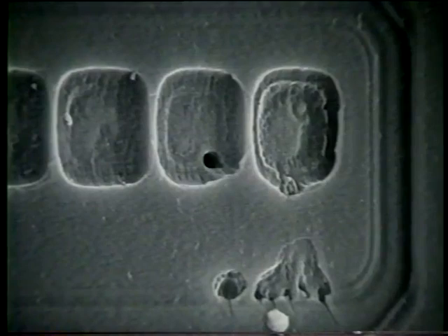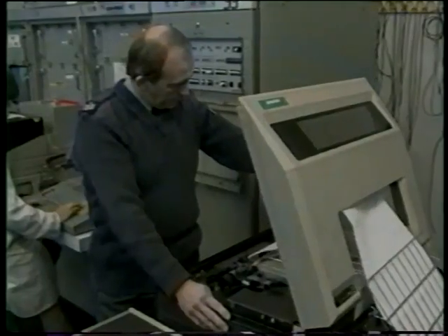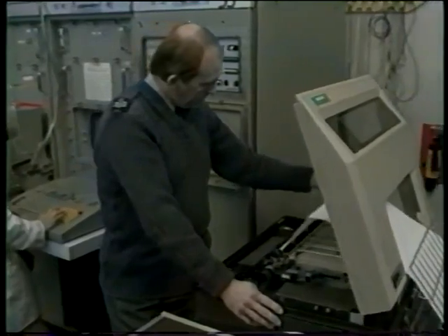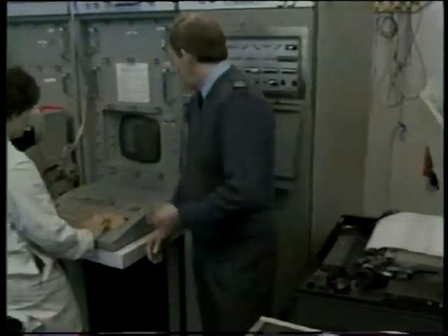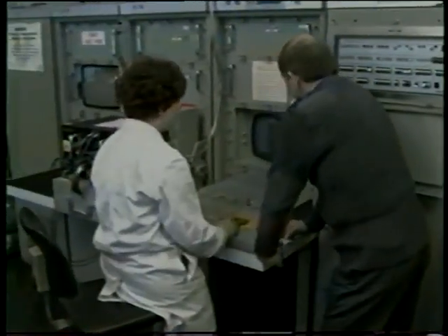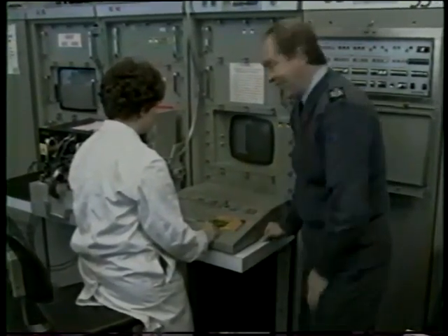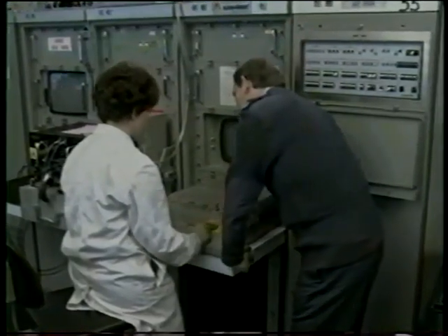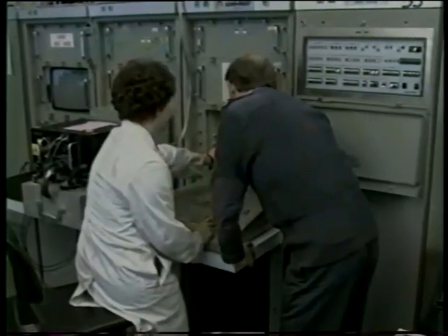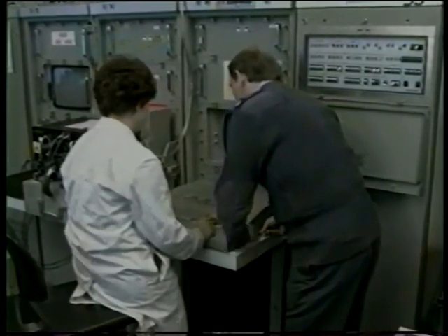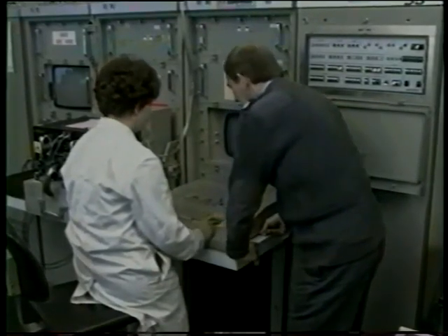By the same means, all kinds of damage can be produced, such as holes or bridging, which can have intermittent effects, especially with vibration or temperature changes during operation. It may even be the cause of all those no-fault fouls you've been putting down to those idiots on the line, or aircrew finger trouble. I can see what you're saying, but... Electrostatic damage can occur to a device from voltage levels far below those required to make a spark, and the technician won't be aware of the damage caused.